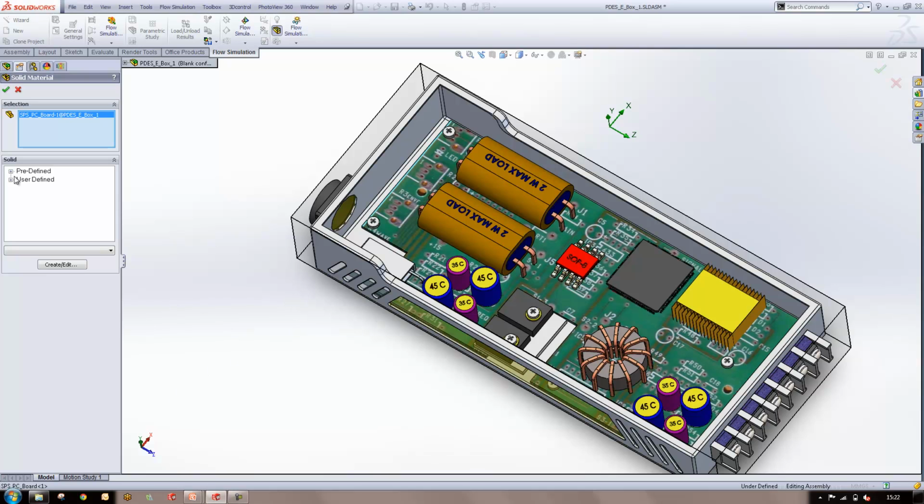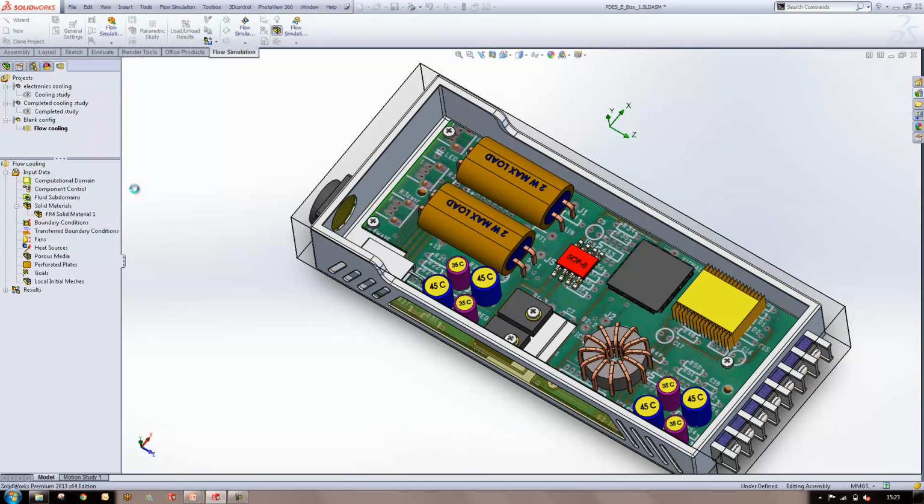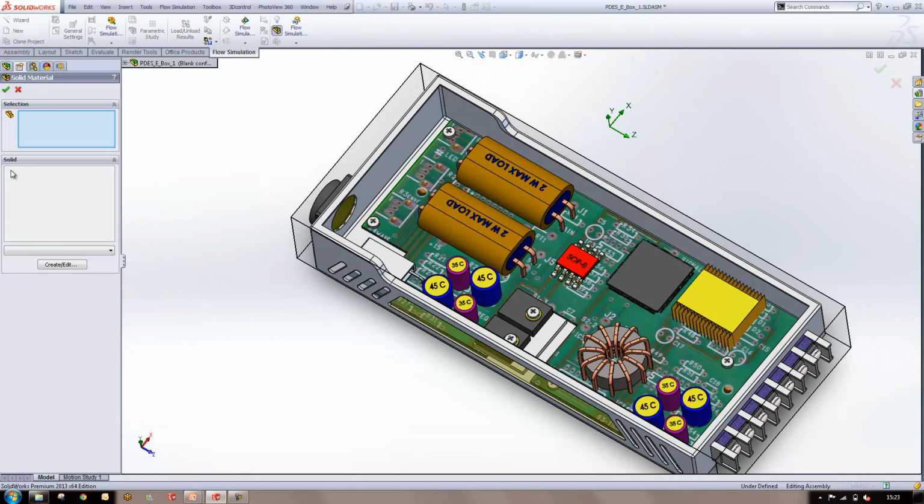But what we can do is grab some of the predefined tools, and inside my laminates I've got an FR4, which is a typical PCB material, and I just hit OK, and you'll see SolidWorks will add that item to the tree, and now everything else will be assumed to be that aluminium 6061 alloy, except our board, which is going to come in at that FR4 plastic. I'm going to do something similar to my heatsink, so let's go ahead and do that.